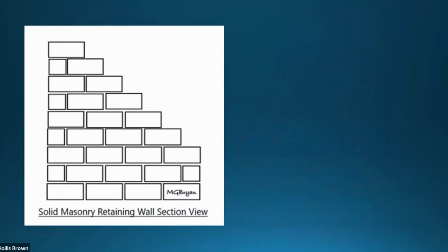And when it curves down a little bit here, it gives it a little push on the front of the wall, but not much. So it doesn't have to deal with freeze thaw like it would in a flat grade situation where a big portion of soil is pushing against it. It's really pushing out above the wall, so it doesn't have that stress from freeze thaw. And also the dead weight of the earth on top of it won't let it rotate either.